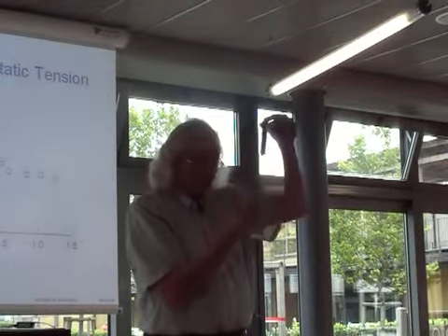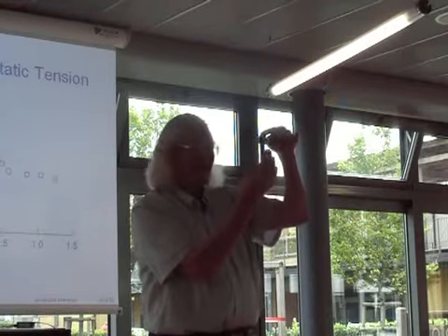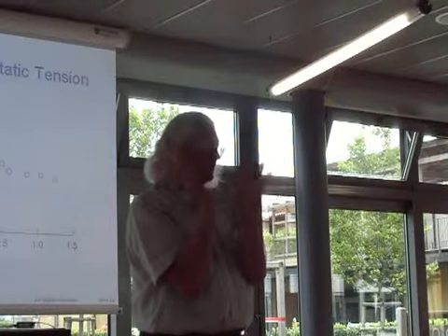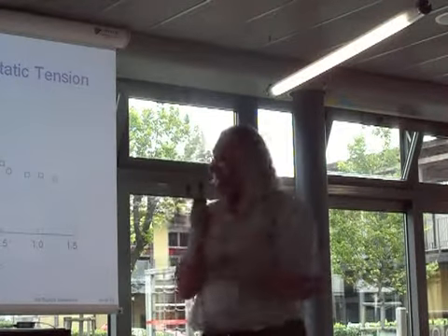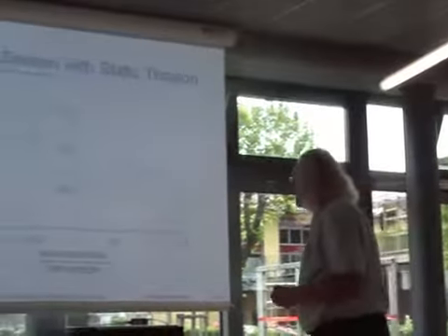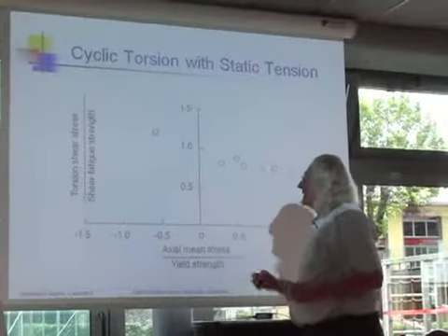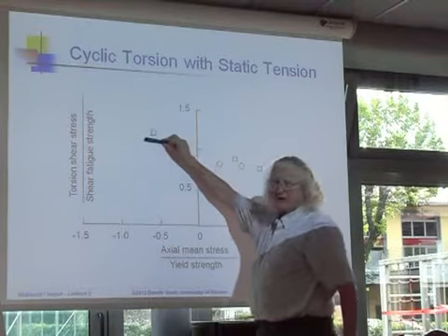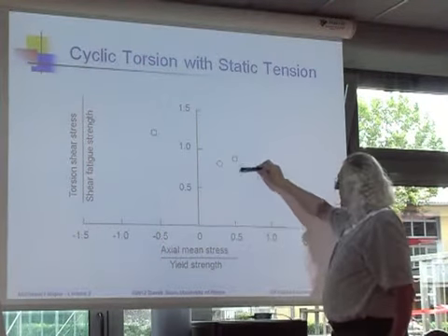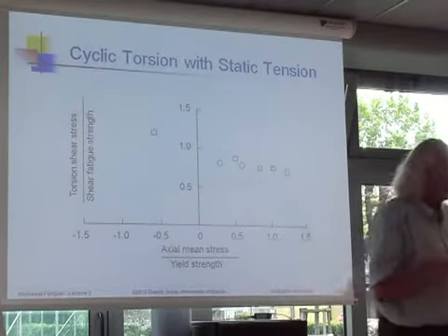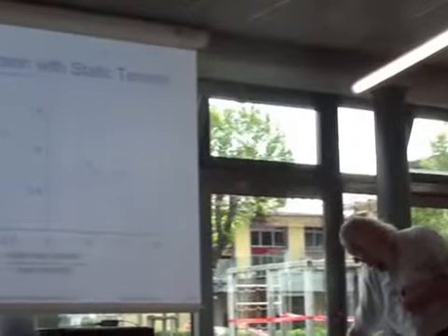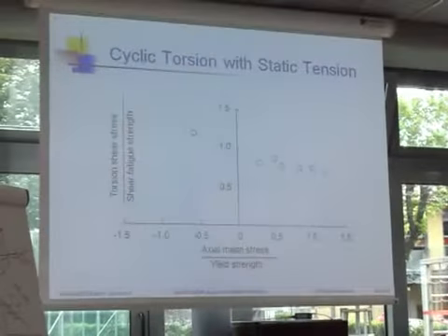And if I push on it, then I will increase the friction that's there, and that should be very beneficial. So that's what we might expect, and that's what you see in the data. So it is beneficial when you have compression, and it is detrimental when you have tension. These are observations from many, many researchers, and this is what Sines summarized.